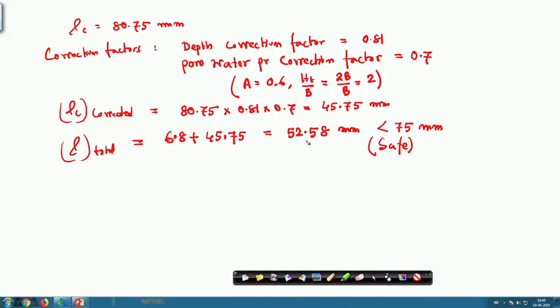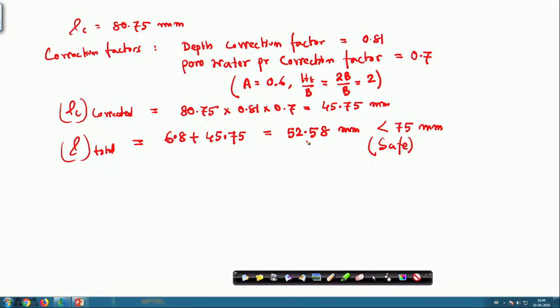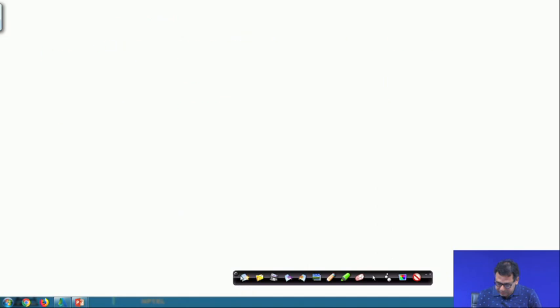Because in our design criteria there are two things. We have to make these foundations such that they are safe against bearing and settlement as well as economical. So, here we can choose this dimension because it is safe against bearing as well as settlement. So, this is the isolated footing part, and then I want to say a few things.